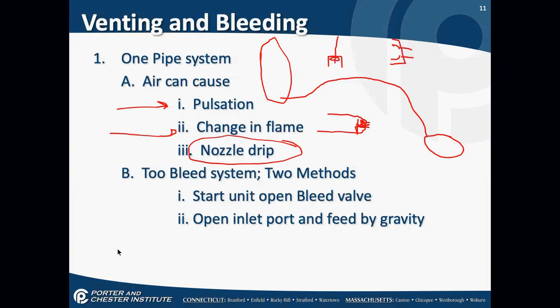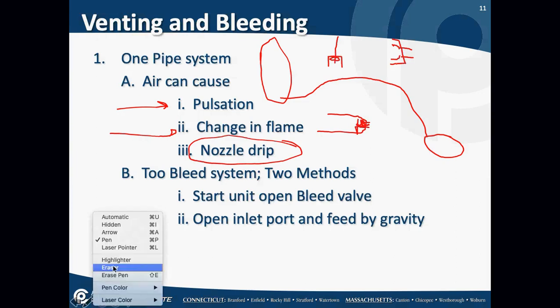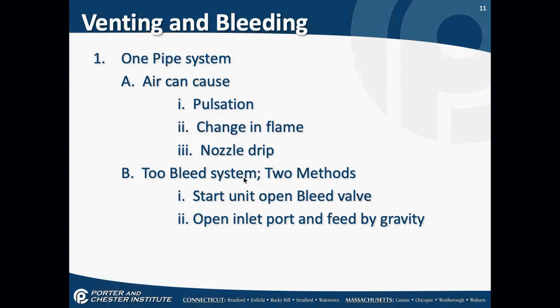That nozzle is hot. That unburned oil will evaporate, and the water will evaporate out of that nozzle. It will actually create a carbon buildup, or what we call coke, on the end of that nozzle and on the end of the nozzle assembly. It will really hurt the burner and the flame as time goes on.